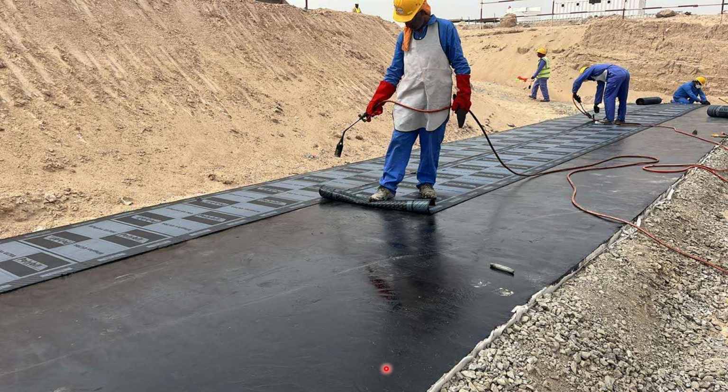In this picture you can see the primer is applied end to end of the PCC, and when the primer gets dry as per the manufacturer recommendation, then we will start membrane application. You can see in this picture we are applying the membrane, and we have to complete it end to end on the PCC. Why? Because this extra area will be left for the foundation waterproofing at a later stage.